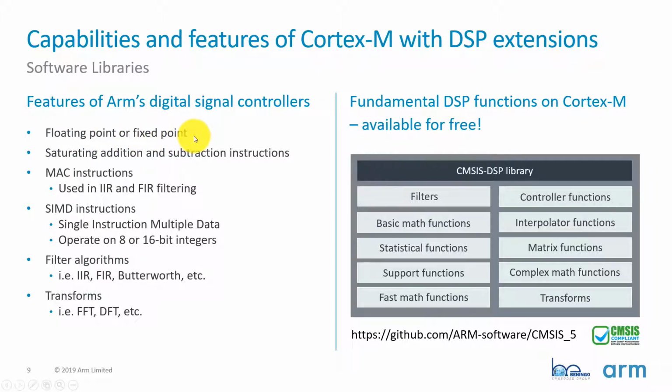A perfect example, there's a series of microcontrollers I've used in the past that were designed for motor control, and they didn't have DSP extensions. So we really had these huge libraries that you had to bring in, and all of the mathematics was actually done using a software library. And they're slower, they take up more code space, which means you can't really get your processor in low power modes. There's a lot more effort to really get these libraries to work the way you expect.